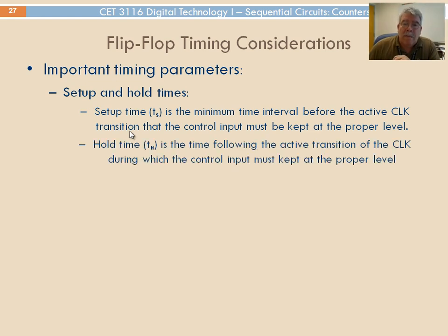Similarly, the hold time is after the clock comes. In general terms, we need to ensure the hold time, in other words, that the input value of the variable is maintained right after the clock transition for that particular time.